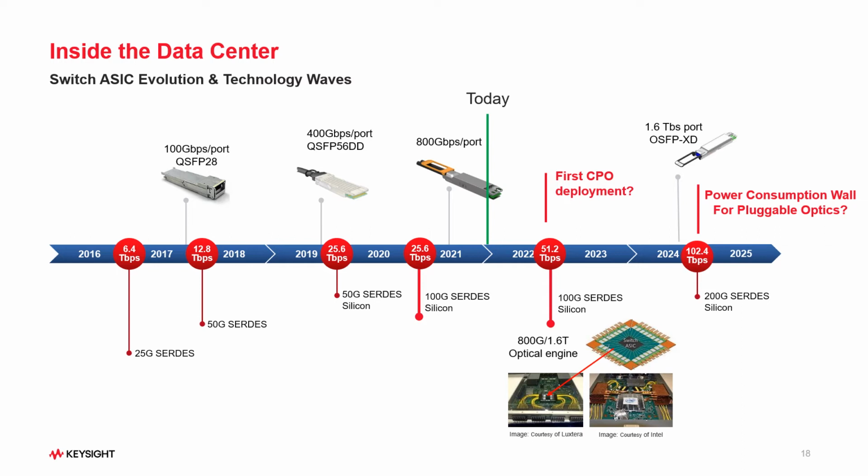Currently, 800G is starting to ramp up, but as we spoke earlier, the 1.6 terabit transmission speeds are also gaining steam. It's typically based on the 224 gigabit per second per lane rate, which has left the pathfinding phase, and the first customers have now received their first ASICs and are already starting with validation tests.